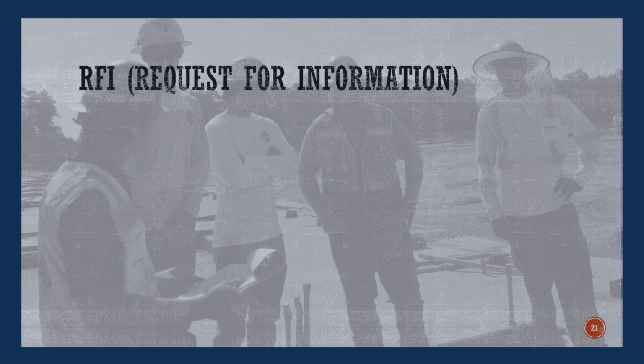So we need to ask this question formally by issuing an RFI. This request needs to go through both the superintendent and the project manager so they can see if they can solve the problem, and if they can't, it heads out to the architect or engineers for some clarification. Communication is key, so make sure you can indicate where on the plans the issue is located, and as always, pictures help.